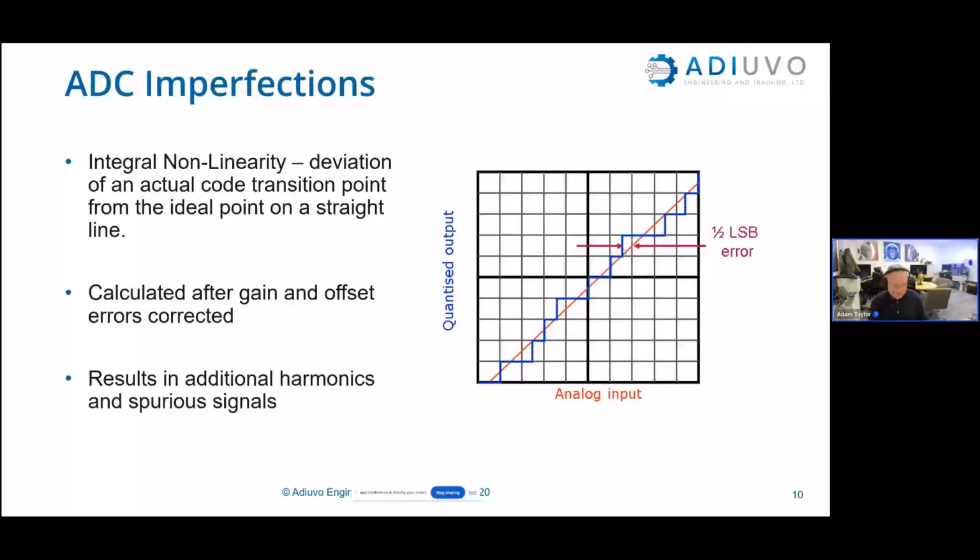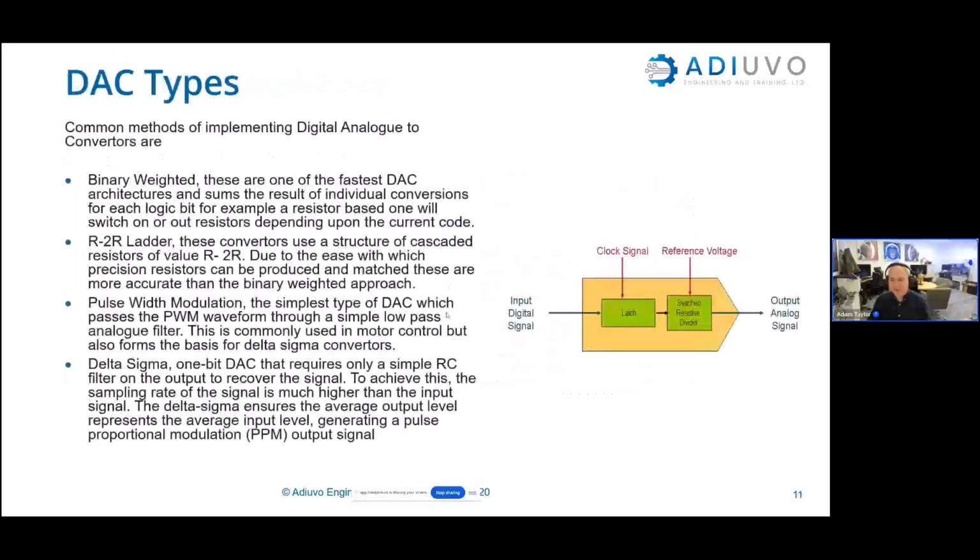These are very important things to consider and look at, because for some applications we don't care. For example, in the XADC application I'm going to show you today, where we're measuring temperature, we probably don't care. When I was doing satellite communications and suchlike, you would really care about spurious harmonics and spurious signals occurring within the communications channel, because it reduces your link budget and your link performance and has a knock-on effect. So we want to make sure that we're working in the best way that we can.